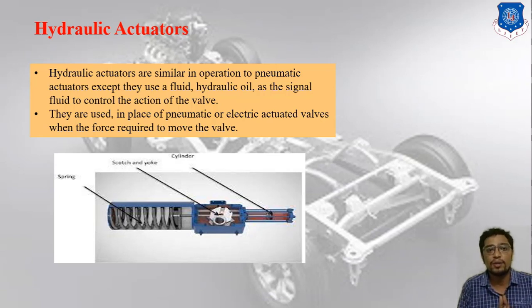So hydraulic actuators are similar in operation to pneumatic actuators, except they use a fluid, as I discussed earlier, such as hydraulic fluid or hydraulic oil as the signal fluid to control the action of the valve. Second, they are used in place of pneumatic or electrical actuators when a large force is required to move the valve. So this is the concept of the hydraulic actuator.